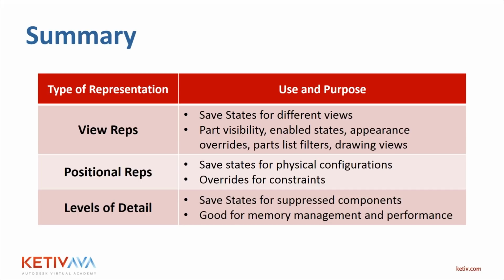And then the other really big thing, I don't know if you covered it, is the browser filtering too with view representations. Say, for example, you've got a subassembly that you really want to focus on inside one of the particular view reps. You can actually expand the folder in that view representation and then lock it down.